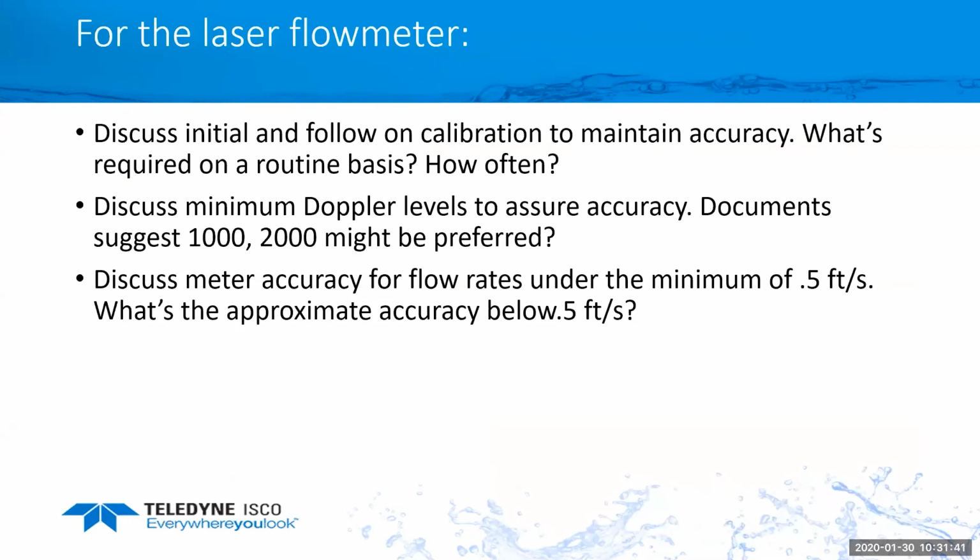Other questions that came in are about the laser flow sensor. I want to discuss the initial and ongoing calibration to maintain accuracy. What's required on a routine basis, how often. I want to discuss the Doppler power. The minimum suggested Doppler power is 1,000, and discuss the accuracy.